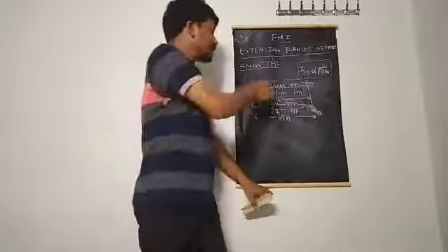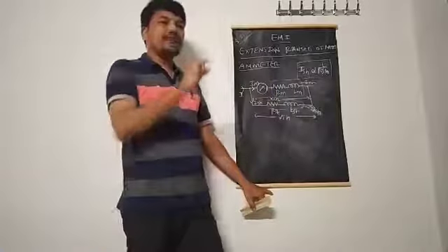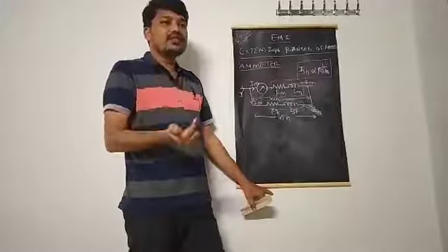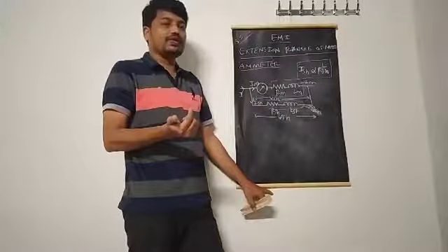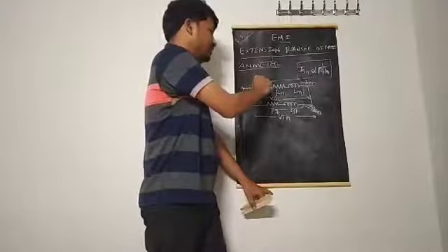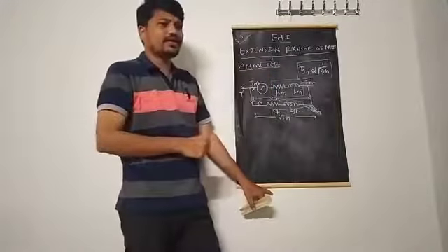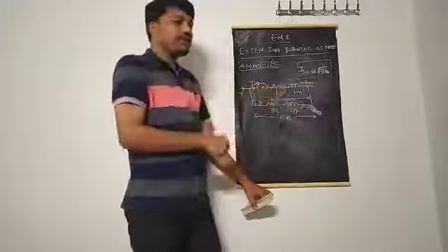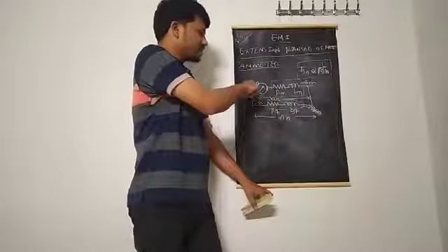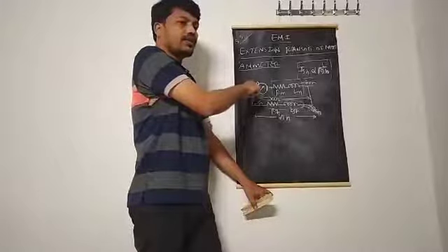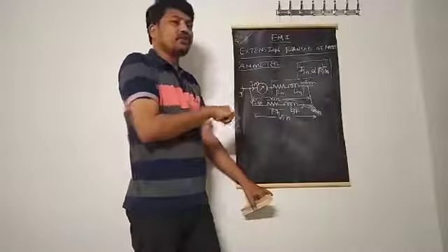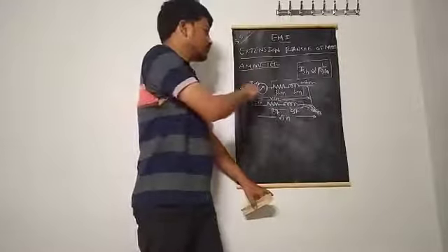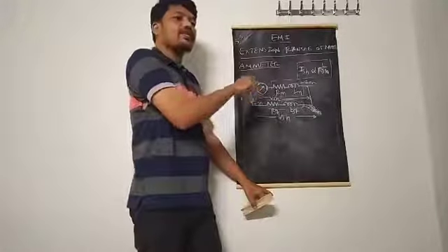This existing meter carries only the meter current IM. Suppose for example we want to extend the range by increasing the current. For example, suppose IM carries 2 milliamps. If I want to measure 2 amps, is it possible? The maximum range of this meter is 2 milliamps. It is not possible, because a 2 milliamps meter does not measure a 2 amps current.